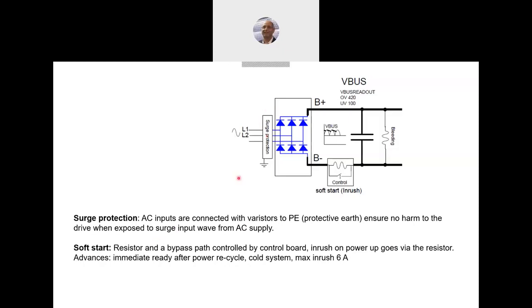The surge protection is for when you get a spike, let's say in winter, that is several times more than the AC input. Then there is a fuse and the spikes will go to the air and not inside to the power stage. In this case, I protect the power stage from blowing.